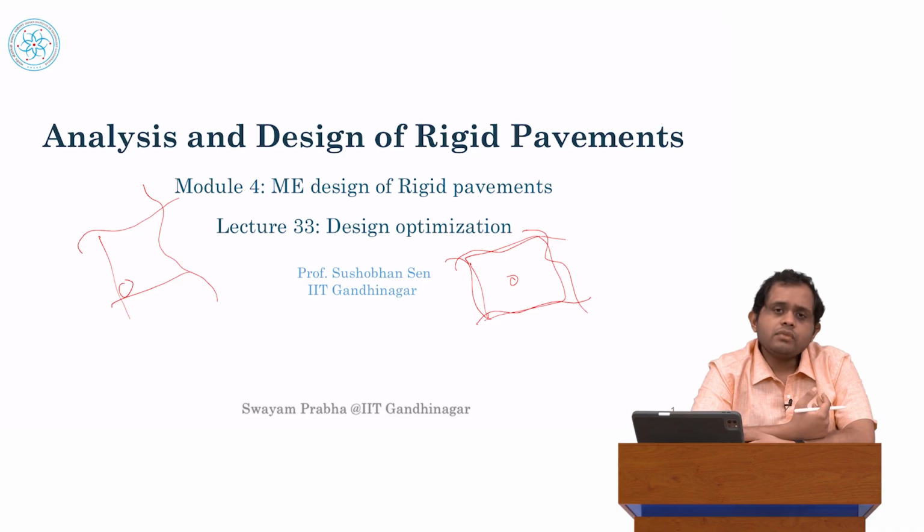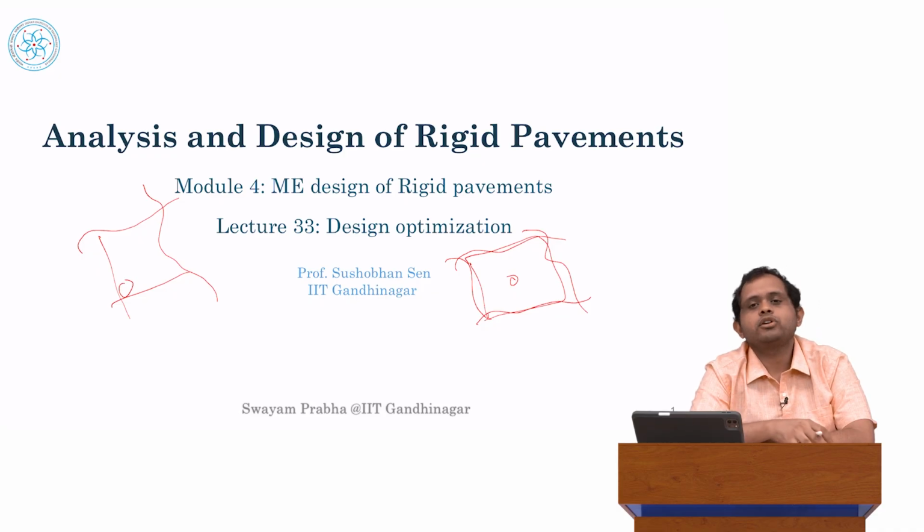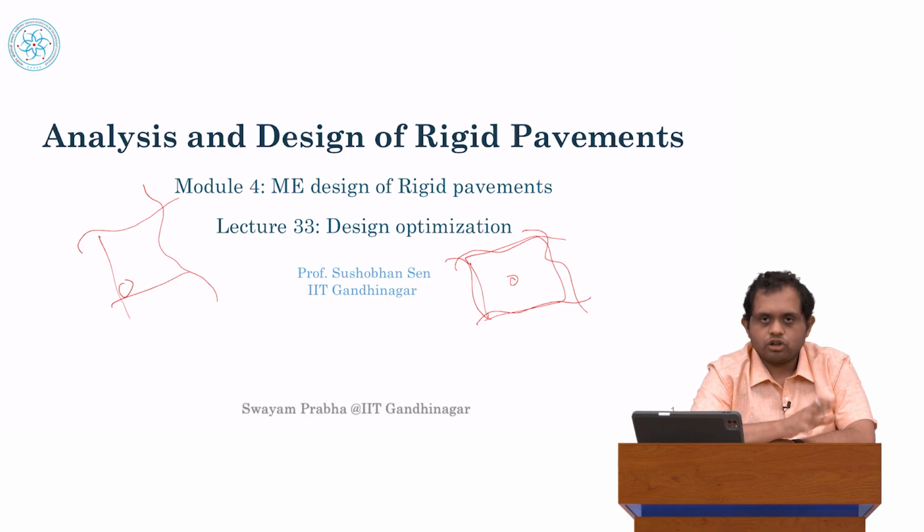The challenge with the finite element method, well, firstly, the basic assumption of the finite element method is that our solution is going to be wrong. We are incorporating an error on purpose into the solution. And we hope that the error is small. We hope that we can make it small by increasing the number of finite elements. So that's one shortcoming, but in practice, that's not a very big shortcoming.